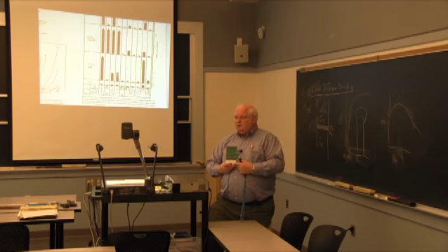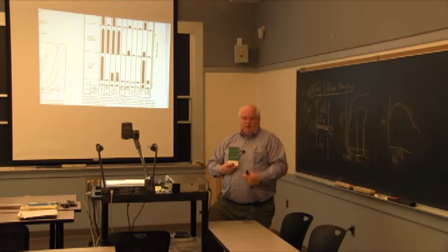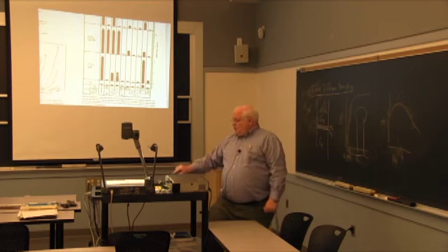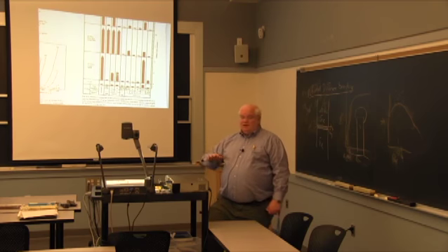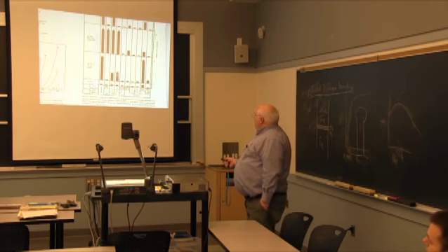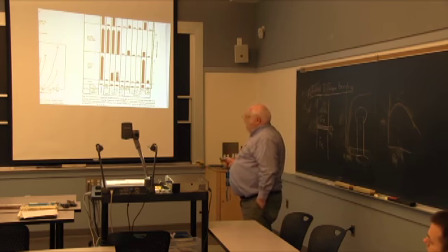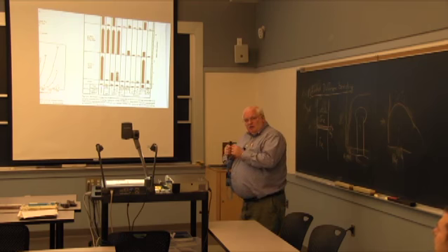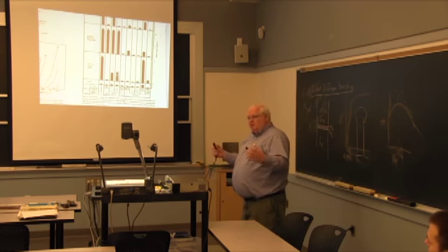Nowadays, in the last 15 years, people have spent a lot of money trying to get the lead out of the solder for environmental reasons, okay? Which has been a big problem because nothing wets as well or as fast as lead tin solder. No one has been able to develop anything, and hundreds of millions of dollars have been spent by industry and government. But in any case, the wetting time, how long it takes on a freshly cleaned copper surface once you get to the melting point to allow the wetting to occur and the flow to start being pulled across by Young's equation,